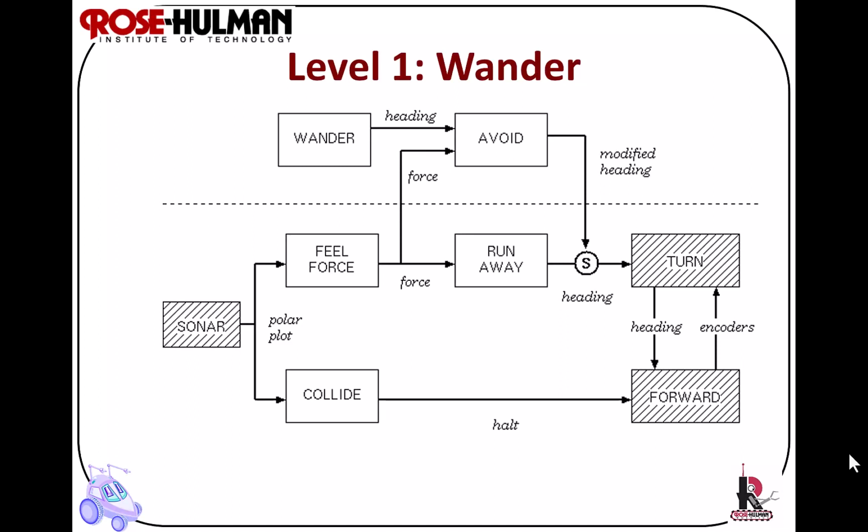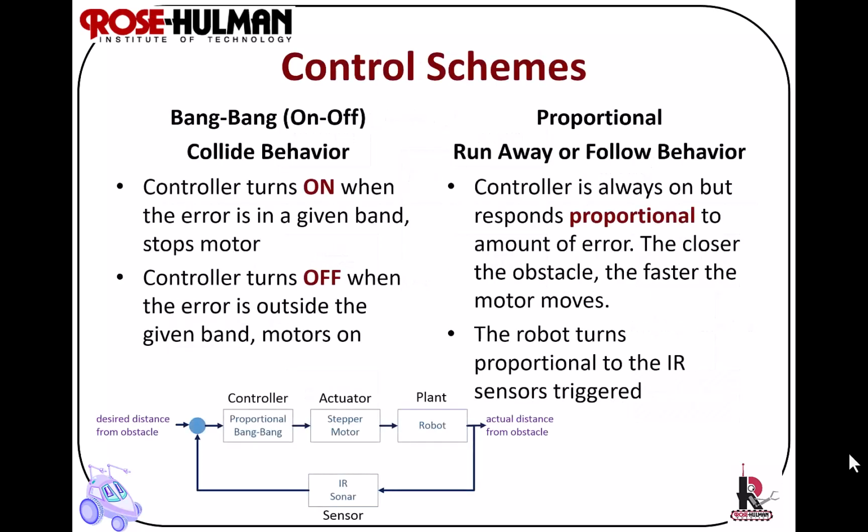And now your state machine will be when you add that obstacle avoidance onto your random wander, so that instead of just moving forward and stopping and either tracking or moving away, it now has a mission to explore the environment, randomly wandering, unless the priority becomes not hitting something in the environment. So it goes into avoid obstacle or it goes into wander.